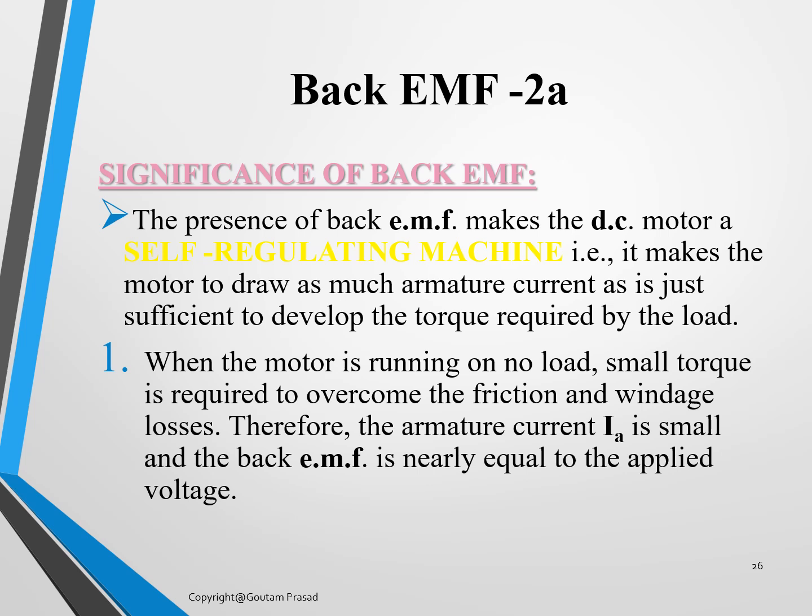When the motor is running on no load, a small torque is required to overcome the friction and windage losses, and therefore the armature current Ia is small and the back EMF is nearly equal to the applied voltage. Nearly, mind it, it is nearly equal to the applied voltage.